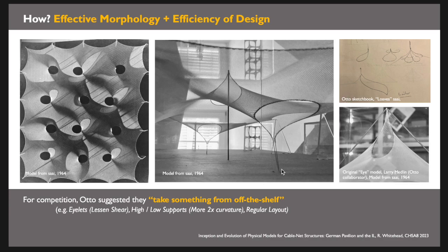You could have really high mass and have really frequent mass, and then have a lot of frequent tie downs, and you could get double curvature that way. But the thing is that really disrupts a lot of the interior space, and it puts a lot of stress on the membrane. Membranes back then absolutely had limits as to how far they could stretch. So instead, the brilliant idea, go high, low, high, low. And in that, you then get more double curvature because the membrane itself only has to span a certain distance, and then it quickly curves the other way, right?